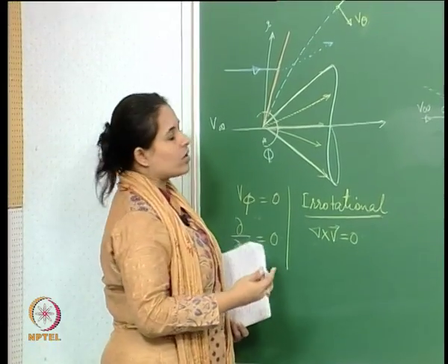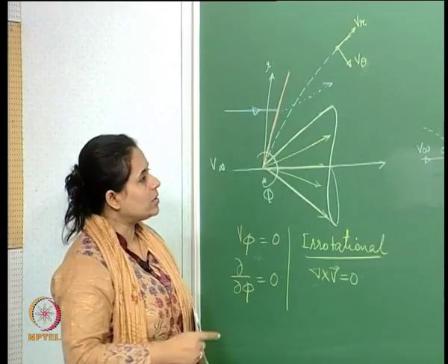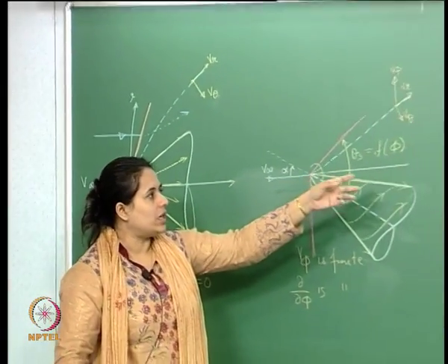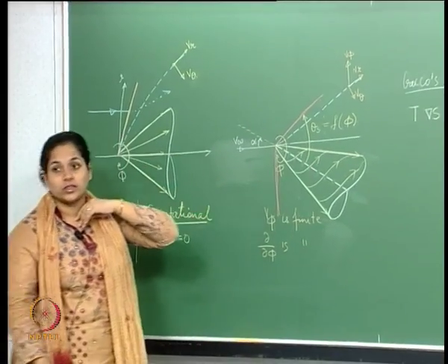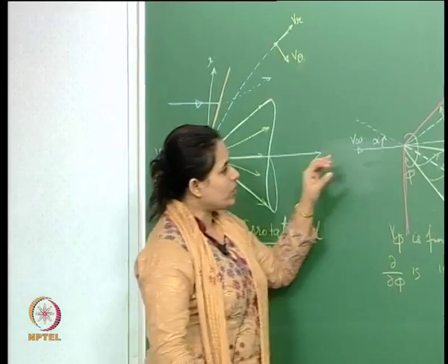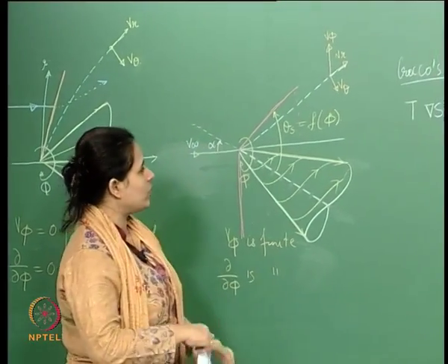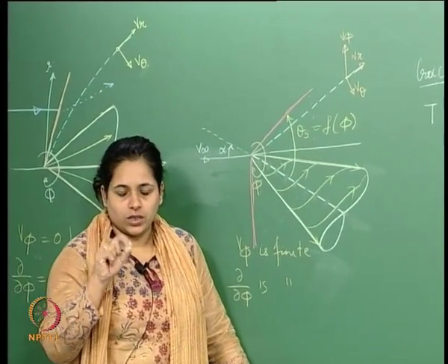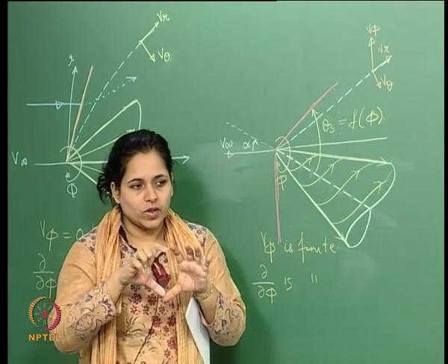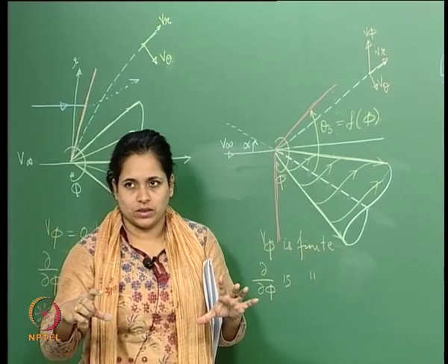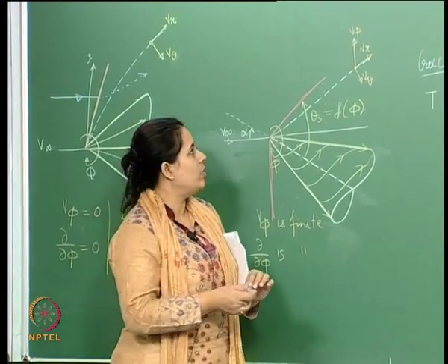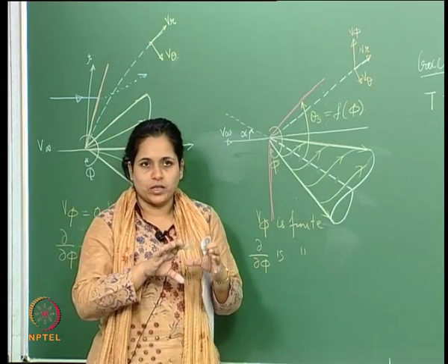So, therefore, it is constant entropy, and hence we can use Crocco's theorem, del H0 and del S are 0, and hence it is irrotational. Here though, that is not the case. If you come to the vertex, then we have a shock structure which is developed, and then I move from one point to the other.